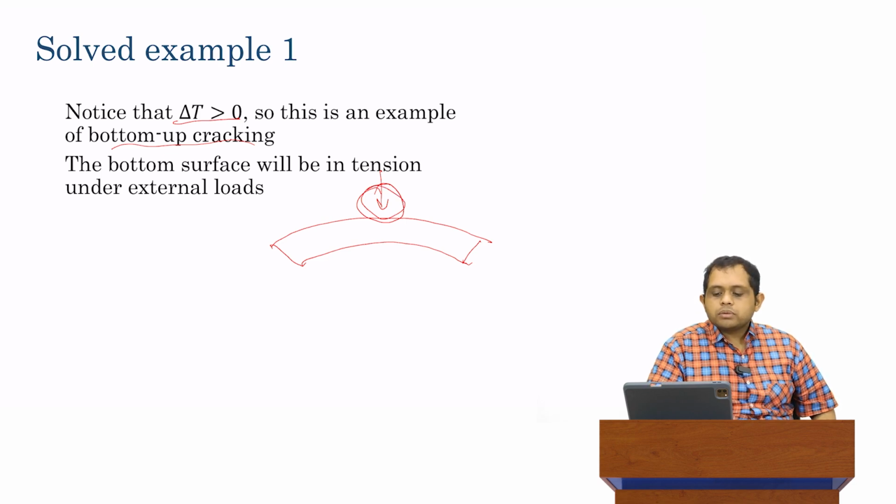In this case, the bottom surface, this little point at the bottom fiber, is actually being pushed apart. As the slab is being restrained, this bottom surface is being pushed apart, and therefore it is under tension. So we actually have tension here at the bottom. Again, concrete is much stronger in compression than in tension. So largely, we are very concerned about the tensile stress. We are not very concerned about the compressive stress. We do actually have compression at the top, an equal amount but of opposite sign. So we're not particularly concerned about the compressive stress.